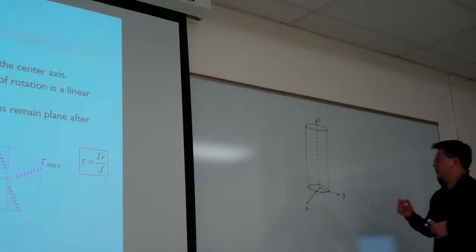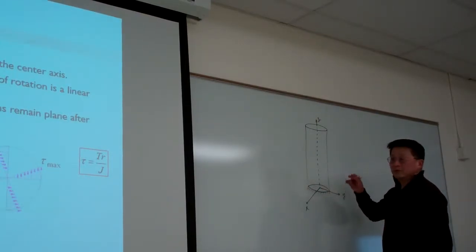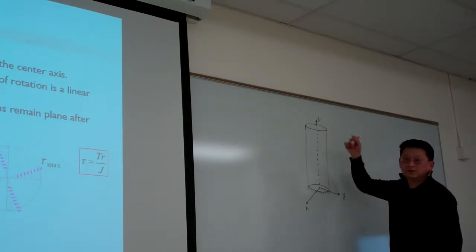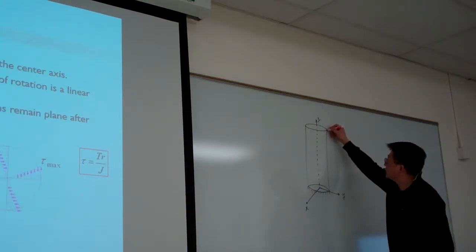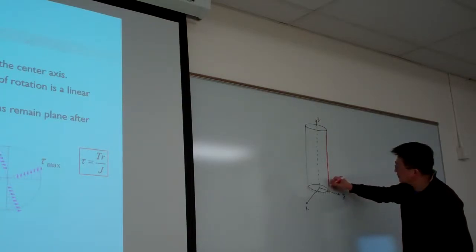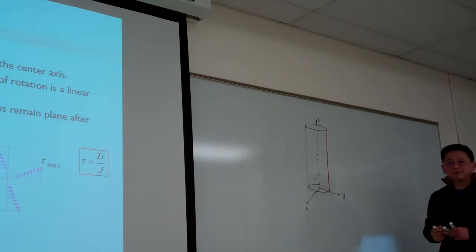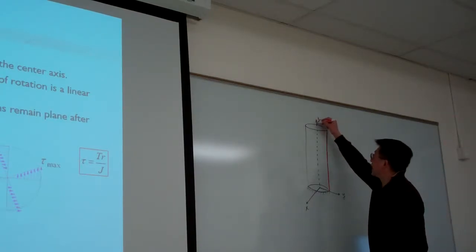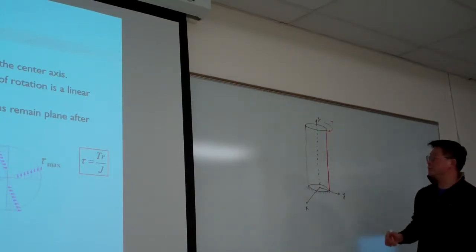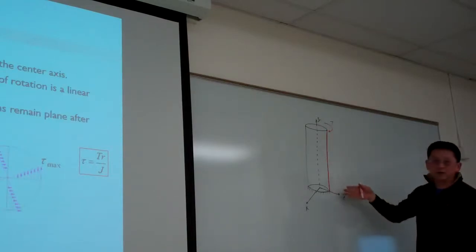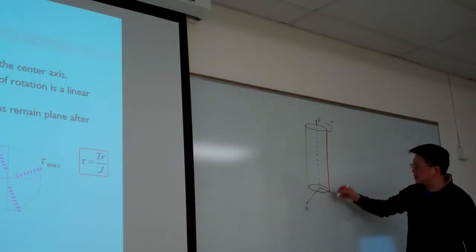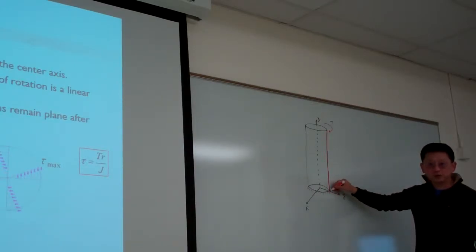Before the torsion is applied, in the undeformed geometry, let me make a mark. Say using a permanent marker, I draw a line on the outer surface, just like here. Then after torsion, if I twist the shaft in this way, this line will remain a straight line on the surface. But because the bottom side is fixed, this point won't change.